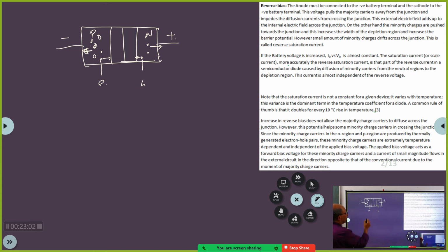Yes, sir. And as far as the depletion layer is concerned, this point of the depletion layer will increase. You remember we discussed this. This point of the depletion layer will increase if the concentration of the minority carriers at this point increases. You remember, with the increase in temperature, the depletion layer width will increase. We discussed it yesterday. Why?